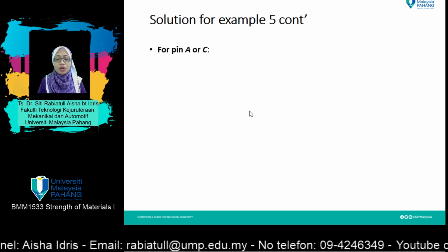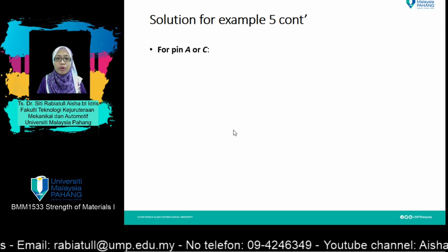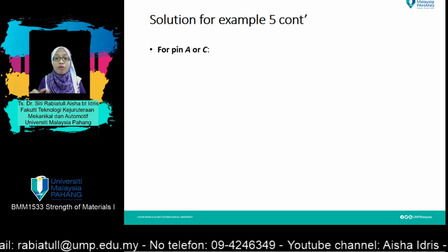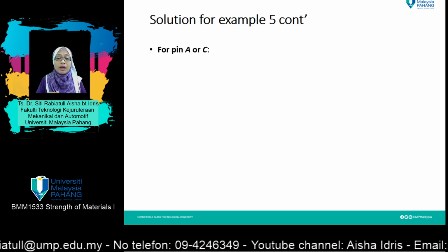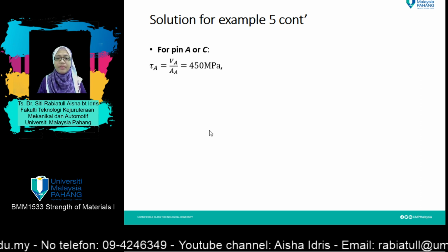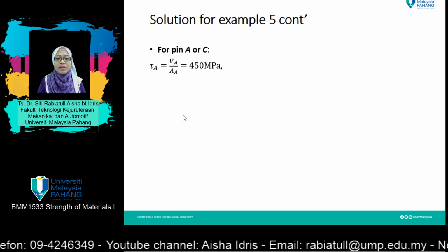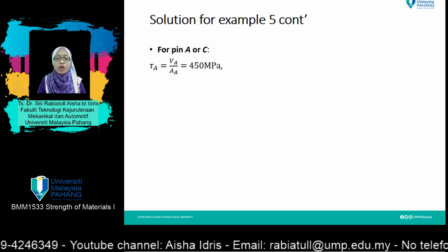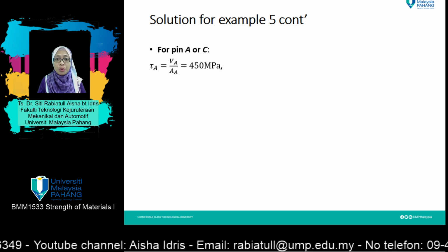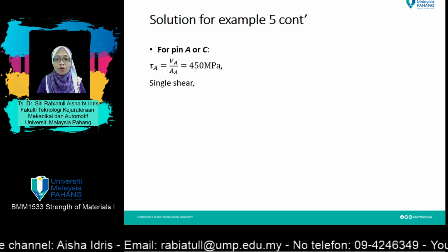You can choose either pin A or pin C. However, the location is the same and the value of forces acting on that pin, either pin A or pin C, is the same. And we know that the equation for shear stress is tau equals V over A equals 450 megapascal, used throughout our calculation in the earlier solution.